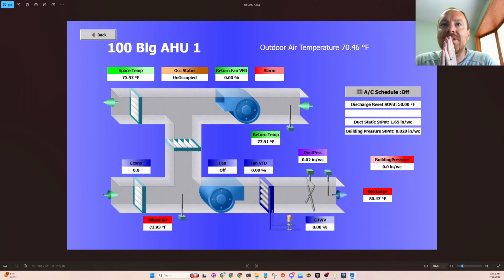Where can we go with this? There's either a problem with these mixing dampers not mixing the air. The outside air temperature sensor and the mixed air temperature sensor should equal each other at 100% outside air, if the dampers are mixing correctly and the sensors are calibrated or somewhat accurate. And there are just a few other odd things that look off in this building.